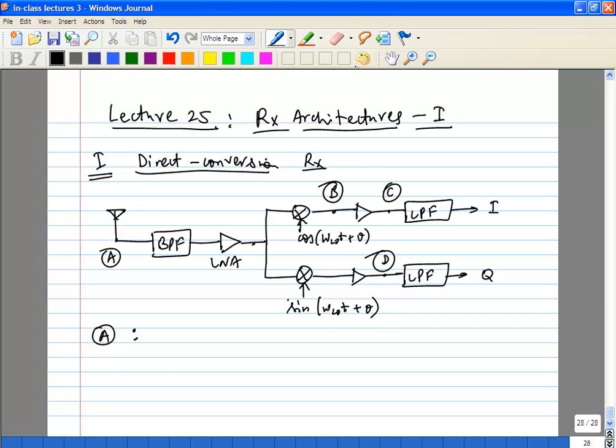In a typical system, if you take a typical cell phone system, this I and Q will have both voice and data. So typically, in modern 3G systems, you can talk and browse at the same time, right? So both voice and data are encoded in the same signal. The digital baseband has to separate out those two. Then that goes into the audio PA.